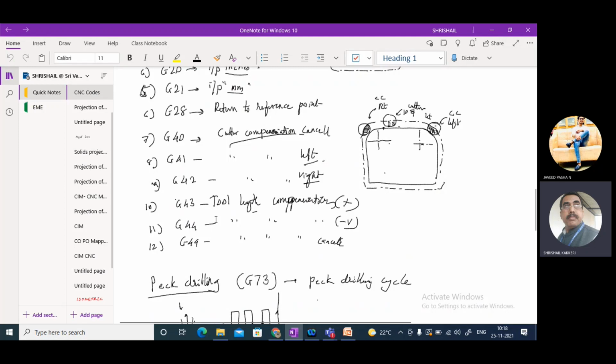Those sensors will be well built within the system itself. While it is working, as I told you, the online inspection of the quality and the online inspection of the tools will be done spontaneously within the system itself. It is a closed loop system. So if there is a change of microns in the length of the tool, that will be compensated itself. That compensation will be taken care of by this.